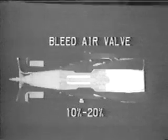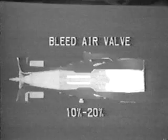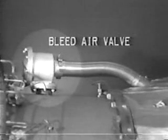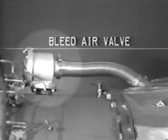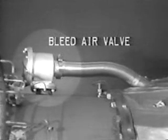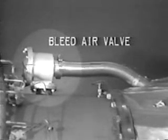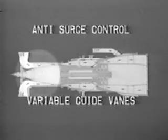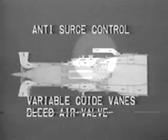In doing this, we reduce the back pressure on the compressor and reduce the load on the turbine. The bleed air valve is used to direct about 10% of the air around the turbine section. Like the variable guide vanes, the bleed air valve is automatically controlled to open during the engine start cycle and close as normal operating speed is approached. Unstable air conditions occurring in the engine are generally called surge. So the anti-surge control during engine start rests with the variable guide vane system and the bleed air valve.